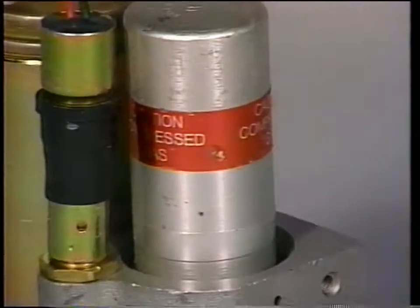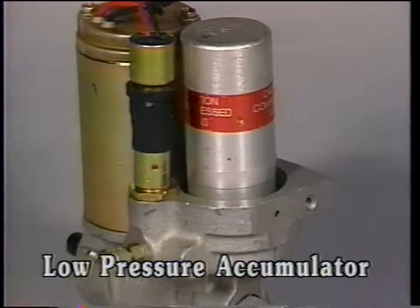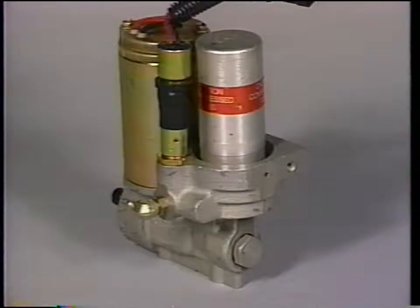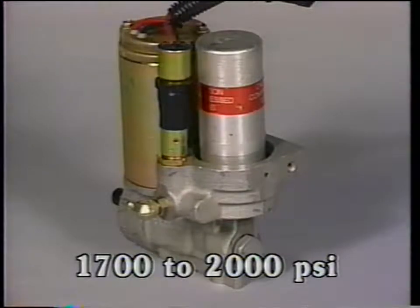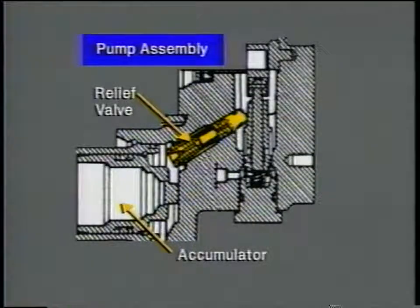The second accumulator might be called a low-pressure reservoir because it is nitrogen pre-charged to only 350 psi. But it can also store fluid at 1700 to 2000 psi. This accumulator is located next to the pump motor.